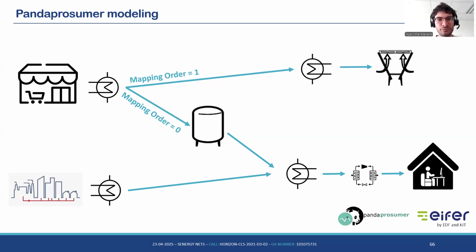And so here I create another kind of parallel configuration, where we have one source, which is the commercial center, and the heat produced can go to two different heat sinks, which are the storage, and then the office demand through the storage, or the dry coolers. And so I need also to define a merit order.